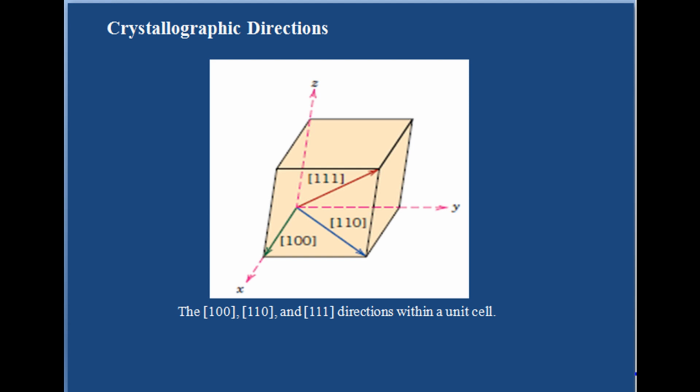We are going to repeat the process. A crystallographic direction is defined as a line between 2 points, or a vector. The following steps are used to determine the directional indices. First step, a vector of convenient length is positioned such that it passes through the origin of the coordinate system. Any vector may be translated throughout the crystal lattice without alteration if parallelism is maintained.